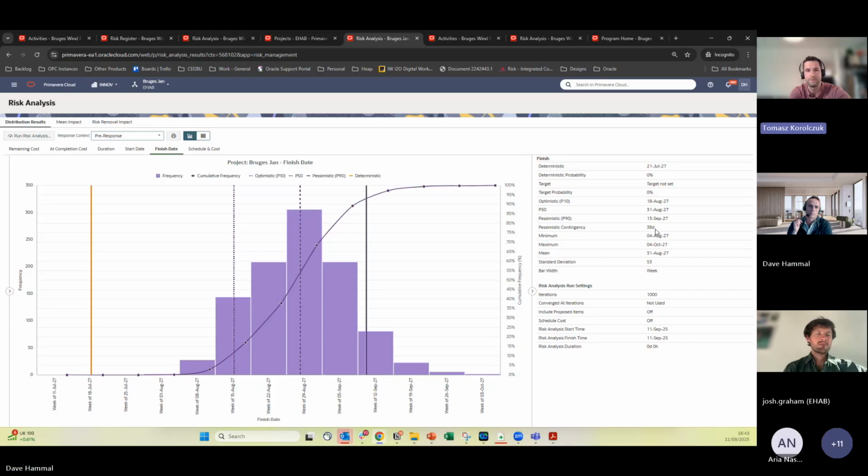if you have slippages. Yeah, and I guess Thomas, you're also touching on the subject of change, and that can be something else that gets pretty complex. When you're going through change on a project, one of the things that often gets missed is that you might be moving activities to a time of the year when weather is going to have more of an impact. Sometimes it's easy to think, okay, that particular change is going to add these 10 days, but you miss the fact there's another 10 days because of the time of year you're getting pushed into.